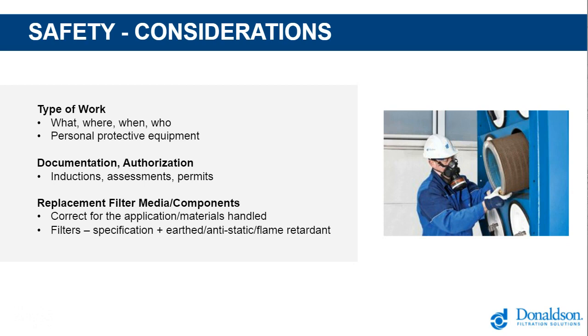Things can change in a collector. Ingredients can change in a process. So we always need to make sure that everything is absolutely appropriate for what we're handling. Whether the filters need to be earthed, an anti-static version, flame retardant, what is the temperature involved? What is the moisture? What are those dust characteristics?